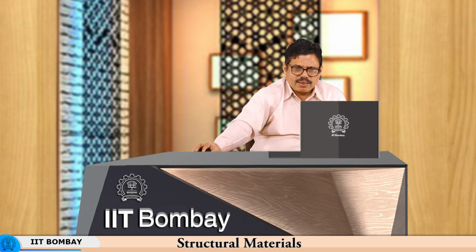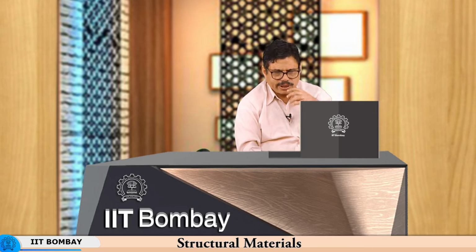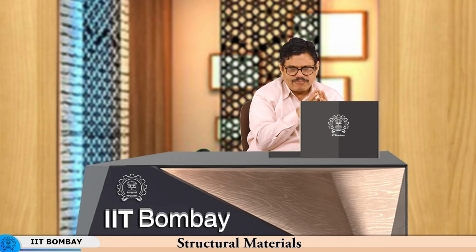Now if you look at the heating schedules for different kinds of steels, when you are doing the heat treatment, you need to heat the material to high temperatures. We have been trying to understand the fundamental that the temperature gradient across the geometry of the product can be deleterious. So, if you have a high alloy steel, if you have large workpieces, that too of high alloy steel, then the heating rate has to be kept at an extremely slow rate.